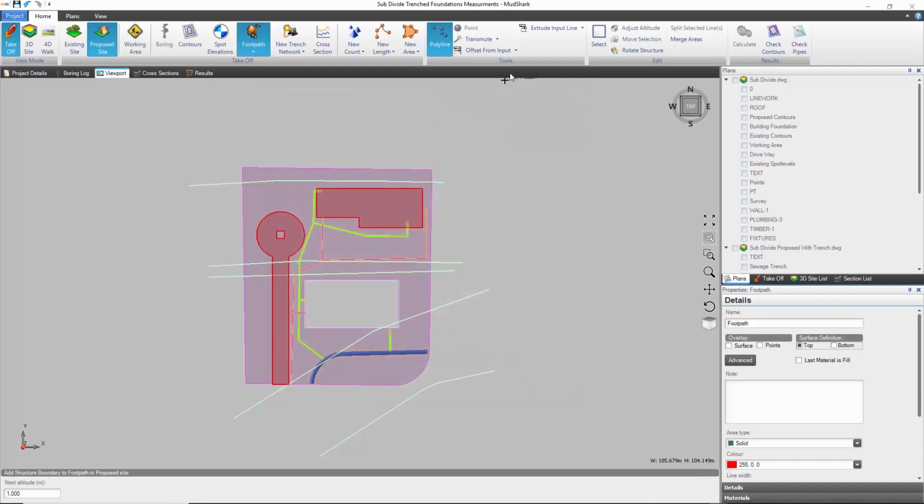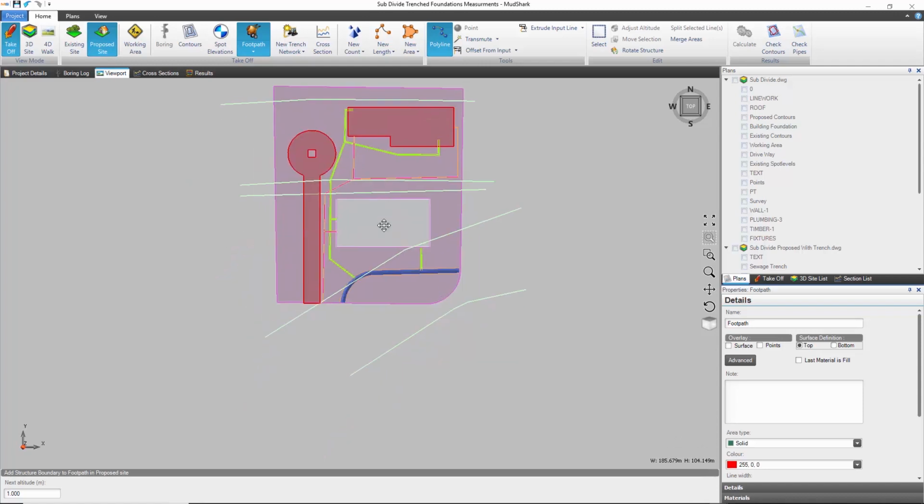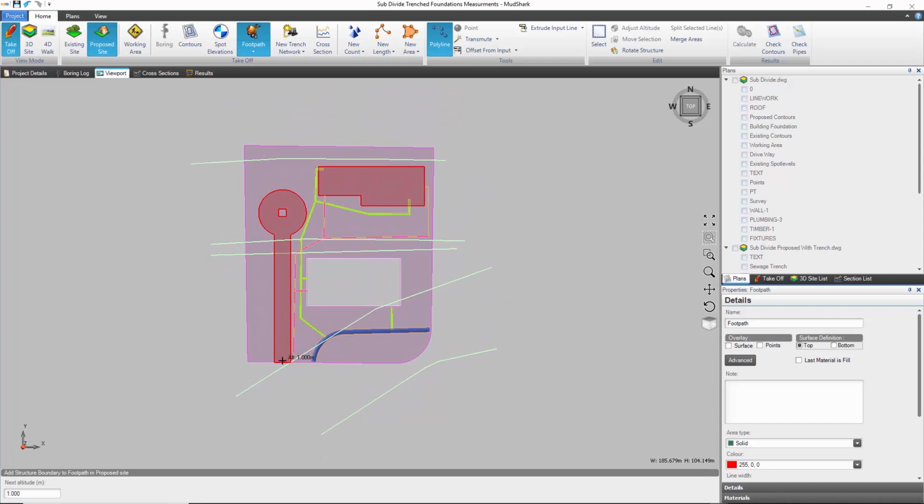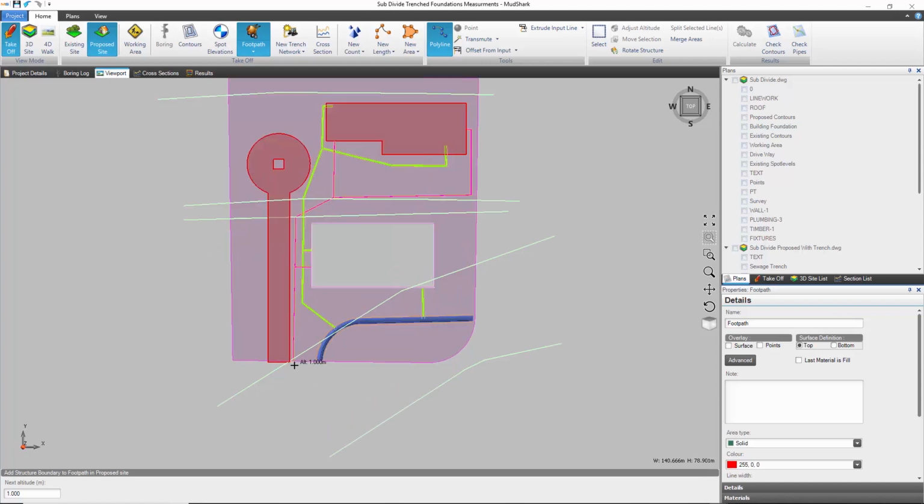So now, as I mentioned, our extrude operations and offset operations work with sloping lines, whereas in version 6 it was restricted to horizontal or flat lines. This gives you a lot more power and flexibility to do things. This is actually a sloping driveway that comes up and then plateaus at the top here with the parking circle. And in addition, we've improved the snapping tools for that.